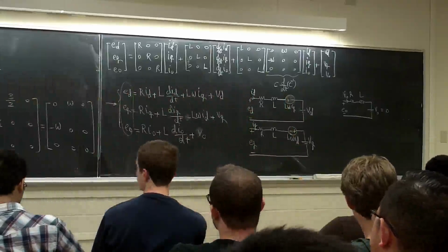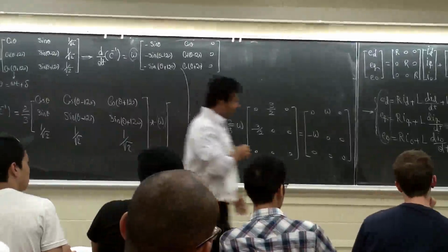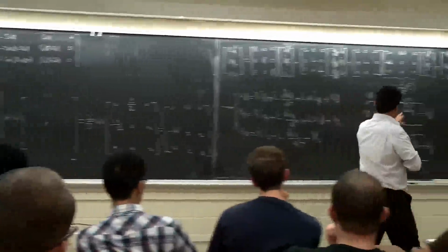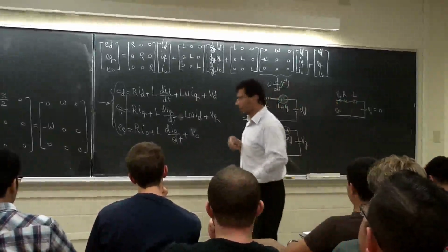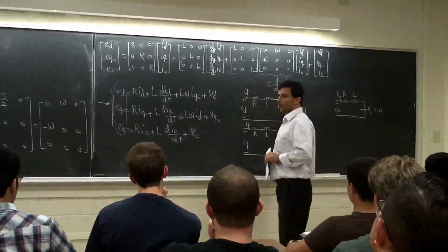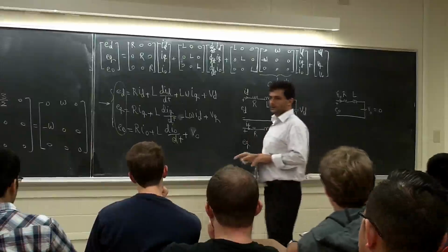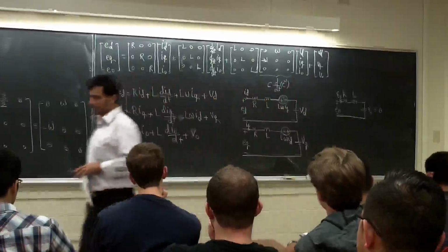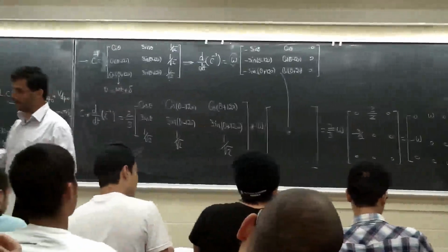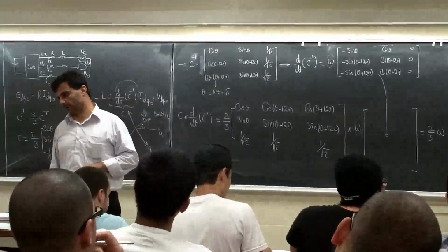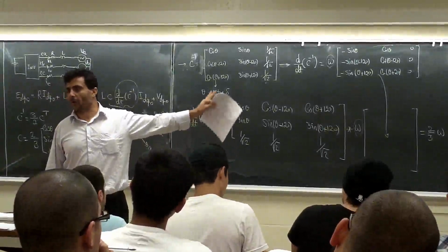Okay. So what is L omega IQ in the system? This one is L omega IQ. This one is L omega IQ. What does it basically mean? See, the D axis is kind of coupled with the Q axis, and the Q axis is coupled with that. I don't like it. I want to be able to control my P, which is IQ, without affecting my Q axis, my D axis, because it's going to change a little bit of the reactive power. Maybe in 3 weeks you're going to see all I'm talking about.